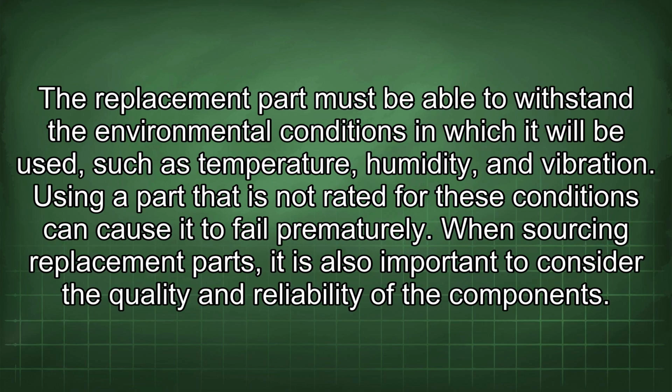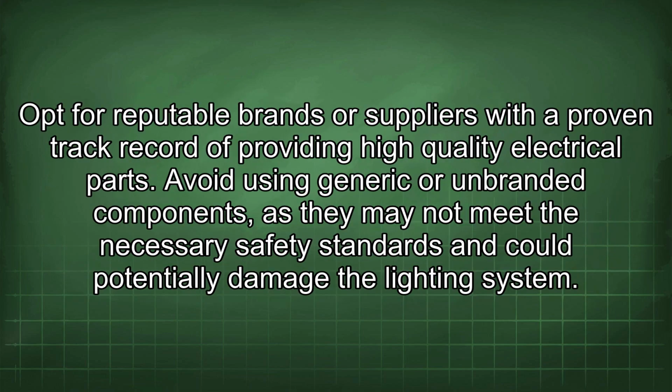The replacement part must be able to withstand the environmental conditions in which it will be used, such as temperature, humidity, and vibration. Using a part that is not rated for these conditions can cause it to fail prematurely. When sourcing replacement parts, it is also important to consider the quality and reliability of the components. Opt for reputable brands or suppliers with a proven track record of providing high-quality electrical parts. Avoid using generic or unbranded components, as they may not meet the necessary safety standards and could potentially damage the